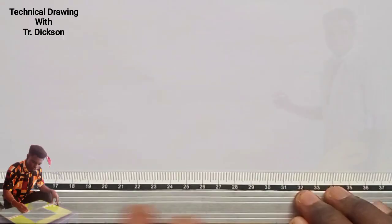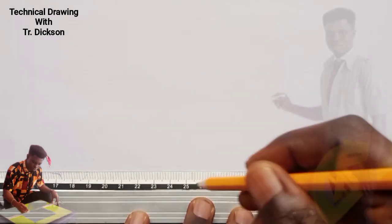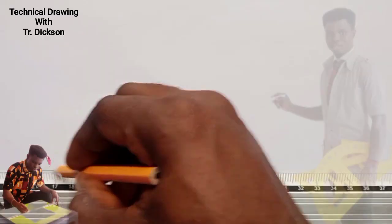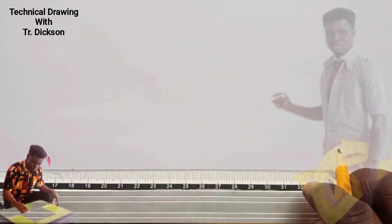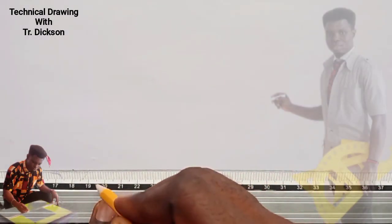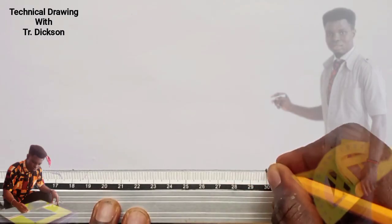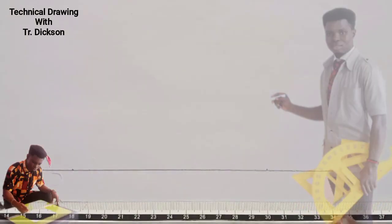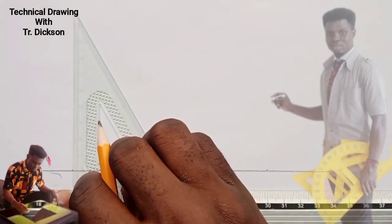Let's get into business. So to begin with, we have to draw the rectangle. And I will want to take the length of the rectangle to be 120 mm. So I first of all start by drawing a straight horizontal line and then fix a point. So that point shows the beginning. And then I will count 120, which is 1, 2, 3, 4, 5, 6, 7, 8, 9, 10, 11, 12. That is 120 mm.